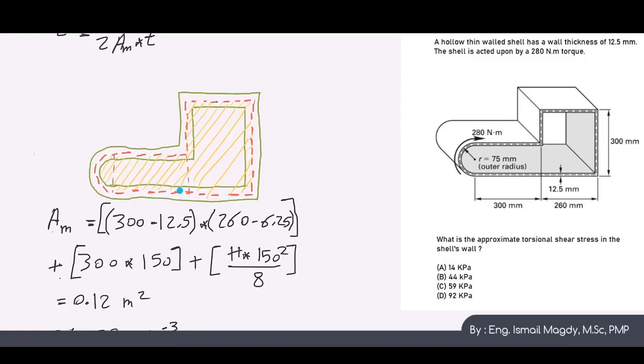But in this case, in the exam, I would calculate the overall area. It would save me maybe 1 or 2 minutes, which is very valuable. And instead of reaching 93 kilonewton per square meter, I would get a little more area. So the result here may be like 91, 91.5 or 90.5 kilopascal. Again, it will be very close to 92, so I can understand that this is the correct answer, because I can see that the other answers are very far from each other.